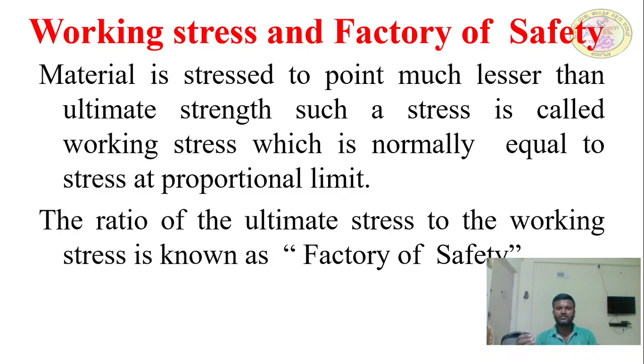For example, for concrete we are using 1.5 as a factor of safety, and for steel we are using 1.15. For soil it's a minimum of 3, and for black cotton soil or clay type of soil we use an even higher factor of safety, even 4 or 5. For wind load, a different factor of safety is used. The factor of safety will change according to the type of parameter we are using, either material or load, whatever that is.